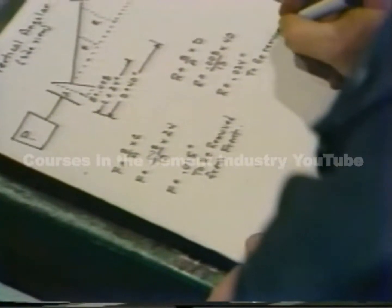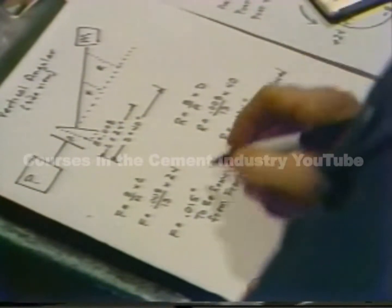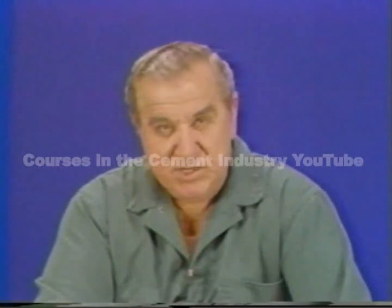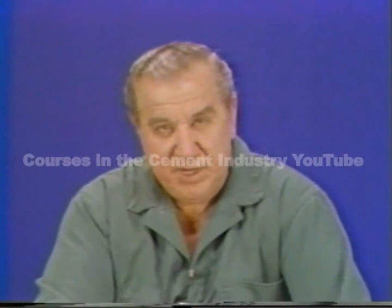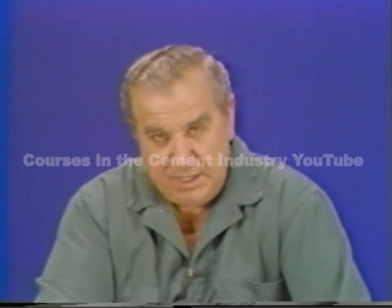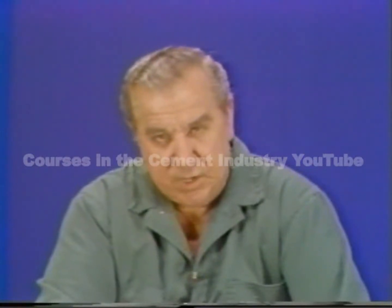He now knows what must be done to correct the vertical angular misalignment. So by using a simple formula, the technician was able to calculate the required shim changes to both front and rear feet in order to level the motor and correct the vertical angular misalignment. Now you'll see the formula again in your text, but let me review it for you here before we go on.